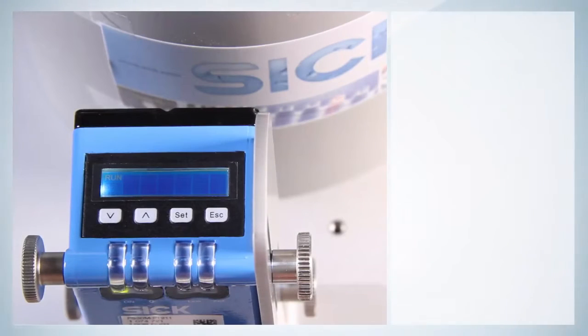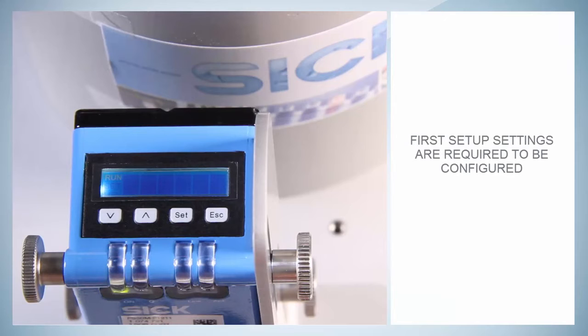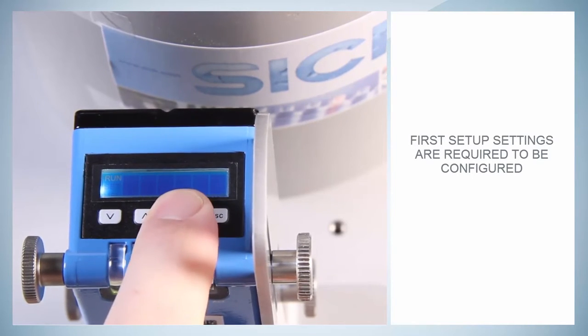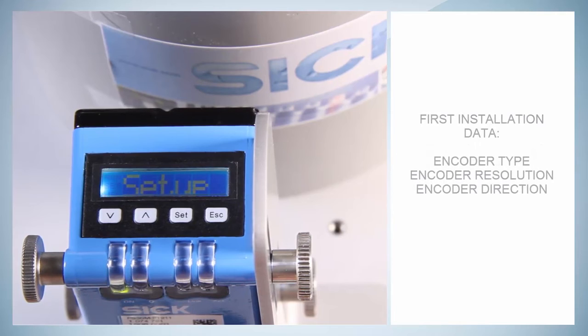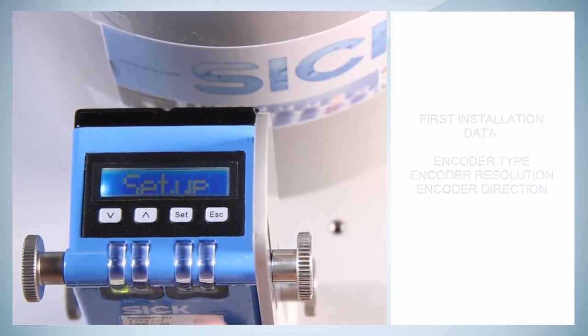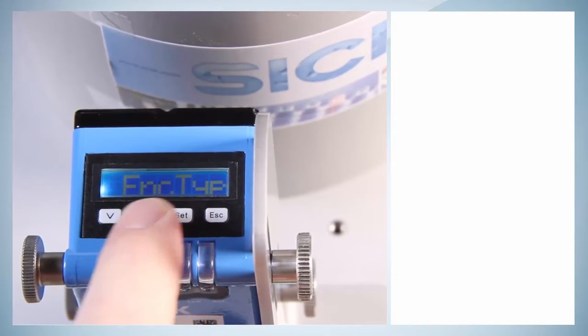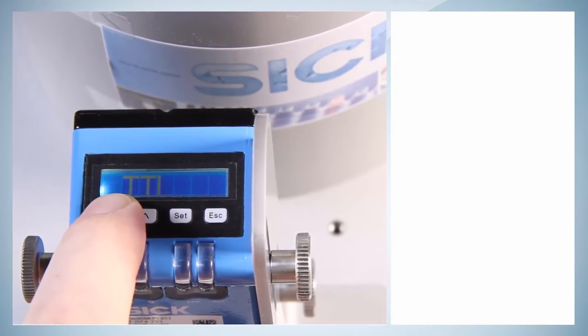After the sensor is connected and has booted, the first setup settings are required to be configured. The sensor asks for the initial values, which are also stored after a restart of the sensor. However, they can be modified in the settings menu. The requested first installation data is the encoder type, the encoder resolution, as well as the encoder direction. With the encoder type, one can distinguish between a TTL or HTL encoder output signal.